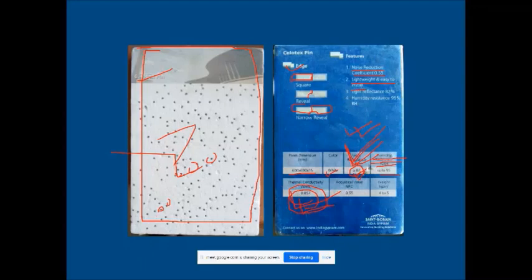So thermal conductivity is 0.057. As we talked about, actually thermal resistivity should be good, and it is a very good sound absorber also. So you can find different properties. Acoustic value NRC that we are talking about right now is 0.55, and it is very lightweight, 4 kg per meter square, right?